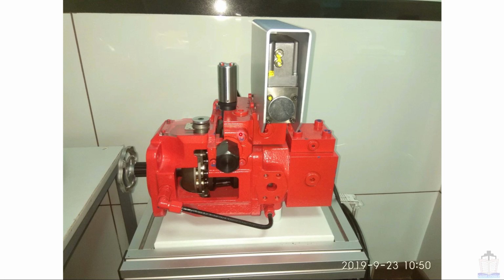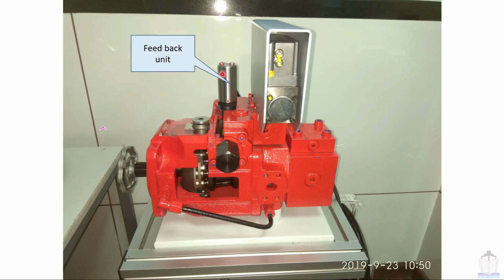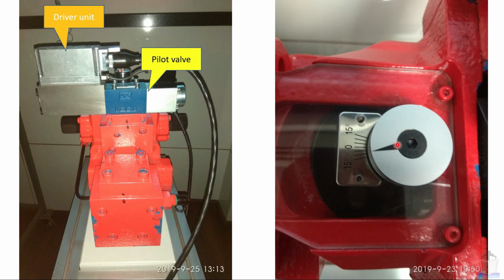This is the engine driven swash plate pump. Here in this area plunger and barrel are situated. This is a feedback unit for swash plate position indication, and this is the hydraulic control valve, also called main valve. This is the pilot valve and this is the driver unit. Now let's have a look from a different angle. This is the driver unit, this is the pilot valve, and this is the angle indicator.